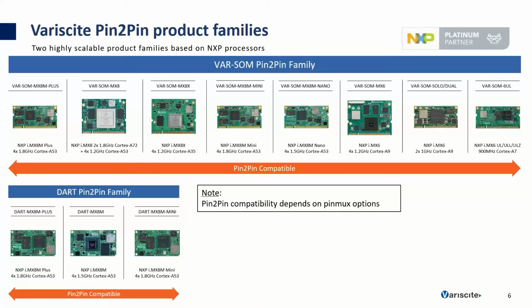All these SOMs are pin-to-pin compatible, but keep in mind that every system on chip from NXP can be configured to have a dedicated pin muxing. So we choose dedicated pin options to make them compatible. The customer is always free to customize their configurations.